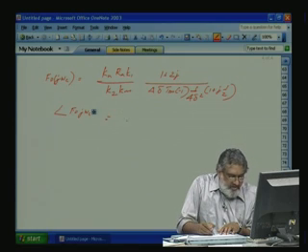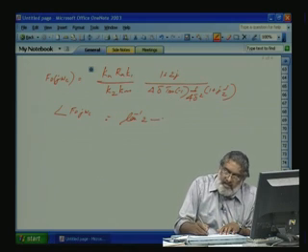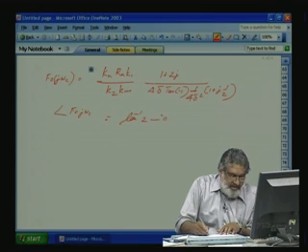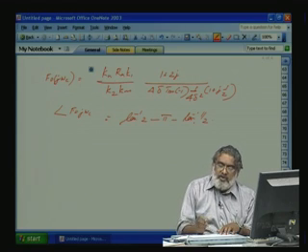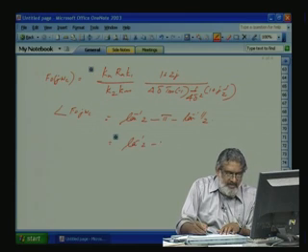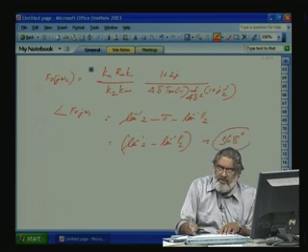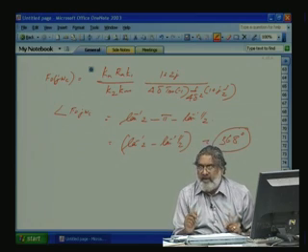The numerator will give tan inverse 2. Because of the minus 1, you have minus pi, and minus tan inverse 1 by 2. So, the phase margin, that is away from pi, will be equal to tan inverse 2 minus tan inverse 1 by 2. This will be approximately 36.8 degrees. So, we got a very good phase margin.